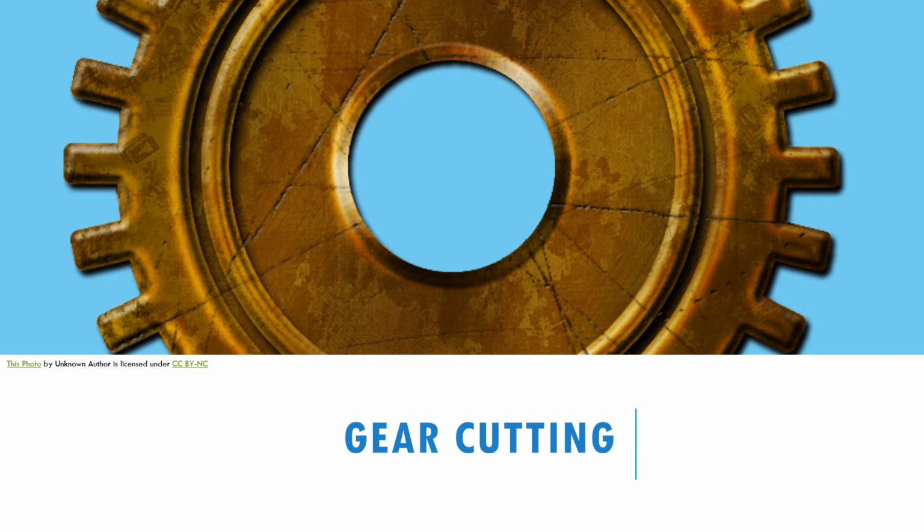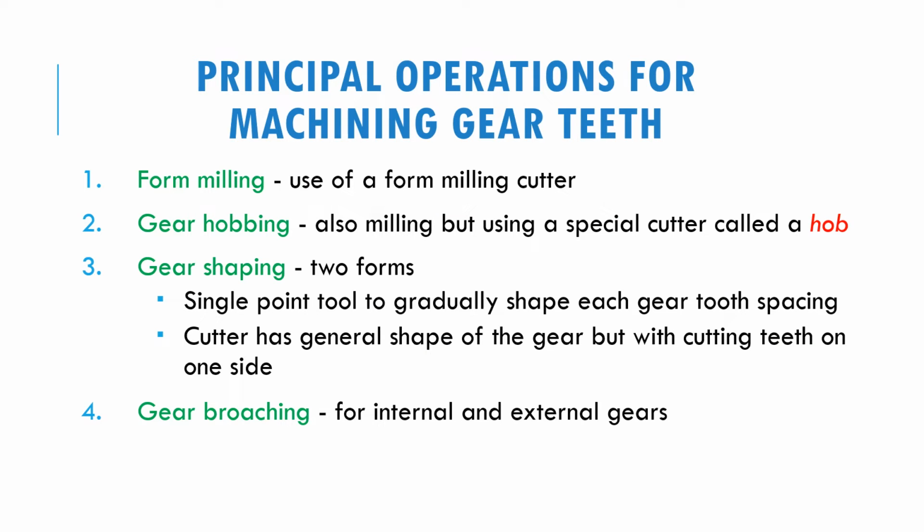The next process that we are going to look into is gear cutting. Now we are looking into the principal operations for machining gear teeth. There are a lot of processes that can be used to machine gear teeth, but in this lecture we are going to look into four types of operation. There is form milling, which uses a form milling cutter to machine the gear teeth. Gear hobbing is also a milling process but uses a special cutter called a hob.